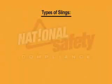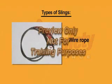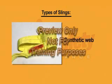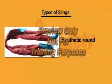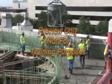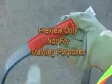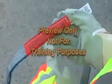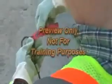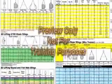There are many different types of slings available to use: alloy steel chain, wire rope, metal mesh, natural and synthetic fiber rope, synthetic web, and synthetic round. Always consult with the manufacturer's guidelines to determine the sling best suited for the lift. Rigging equipment should never be loaded in excess of the recommended safe working load as prescribed on the identification markings by the manufacturer. Sling manufacturers provide charts specifying the load capacity, allowing you to determine what size and strength you need for the job.